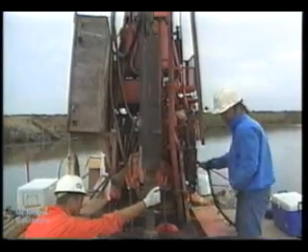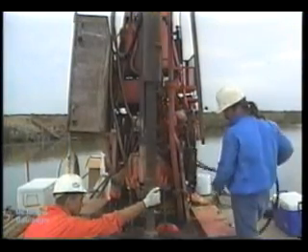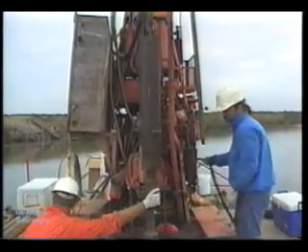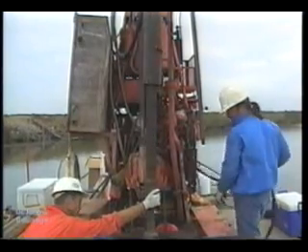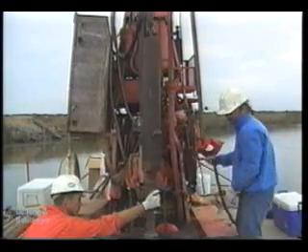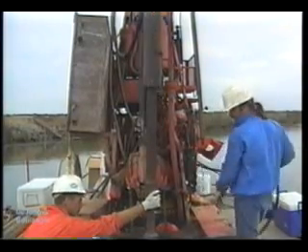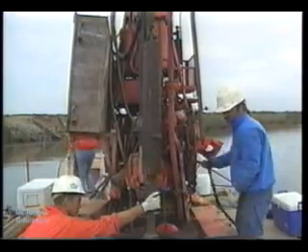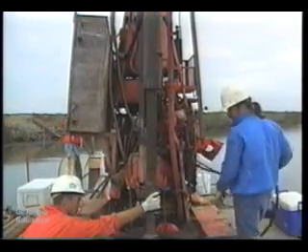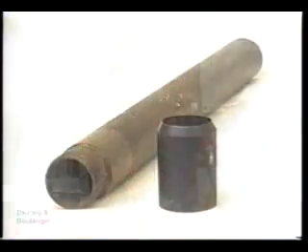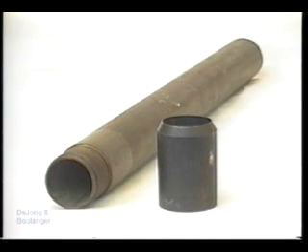When mud rotary drilling in cohesionless or highly erodible soils, an outer casing is used to create a closed circulation system. Casing is advanced concurrently with drilling until it is seated in dense, unerodible soil or rock. A shoe, made of hardened steel, is attached to the bottom of the lead casing to prevent the casing from buckling while it is driven into the soil by the hammer.